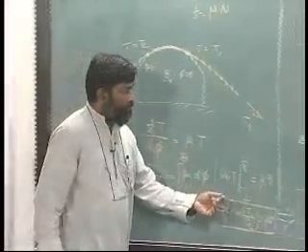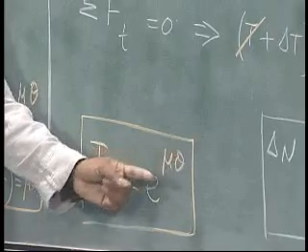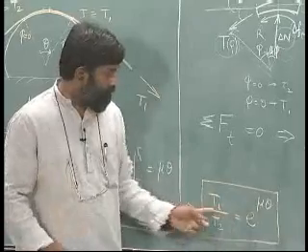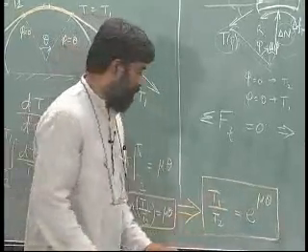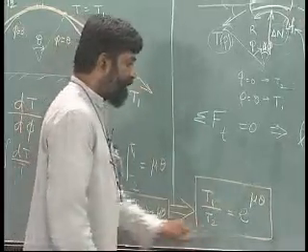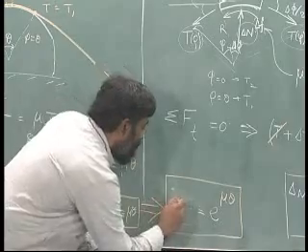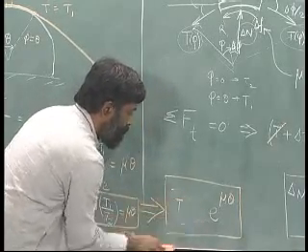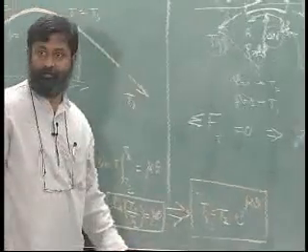Now, remember, the ratio is an exponential of theta. So, as theta increases gradually, T1 increases exponentially with respect to T2. So, another way of writing this is, instead of writing it like this, T1 equals T2 times e raised to mu theta.